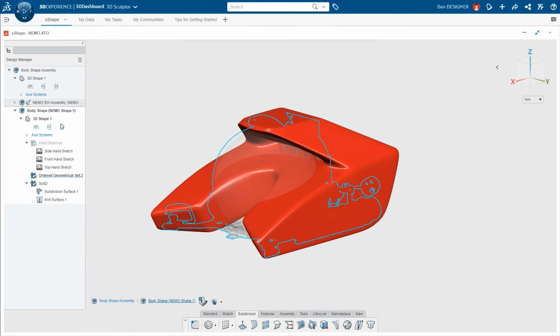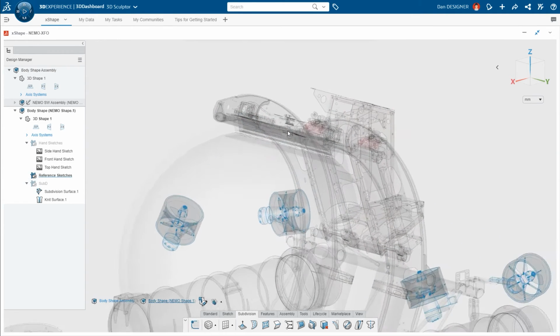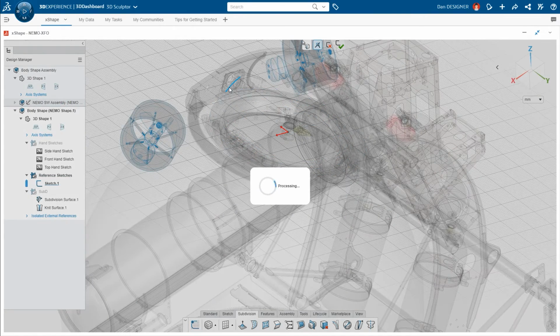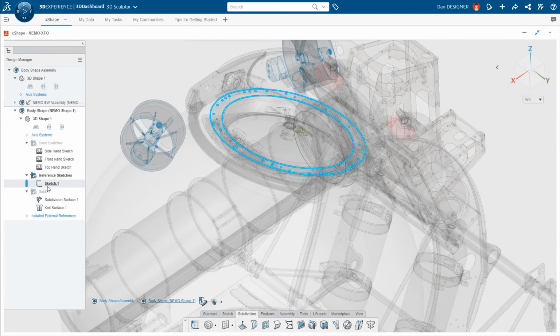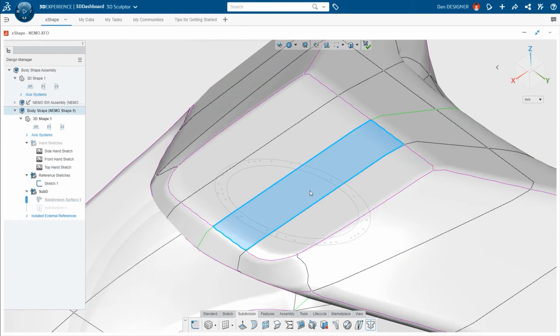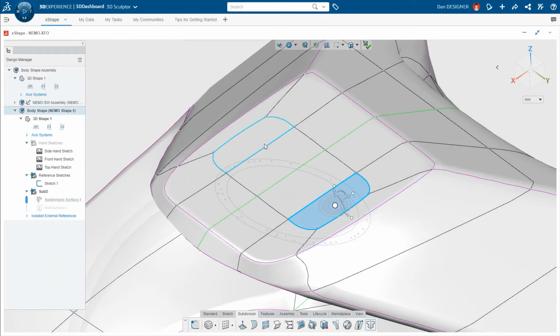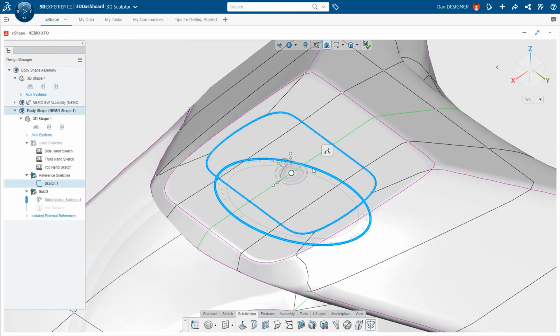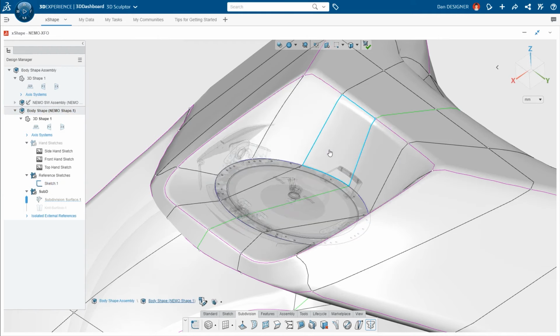To keep the design tree organized, Dan creates an ordered geometrical set to house his reference sketches. By converting the outer diameter of the hatch opening, he'll have a clear view of the edge he'll need to blend the opening of the hood to. Rather than adding a loop of vertices surrounding the entire perimeter of the body, Dan can add a localized group of entities with the subdivide command. Now he can select the new loop of edges on the hood and the corresponding edge on the hatch. Magically, the Align to Curve command perfectly aligns Dan's X-shape geometry to Don's SOLIDWORKS assembly.